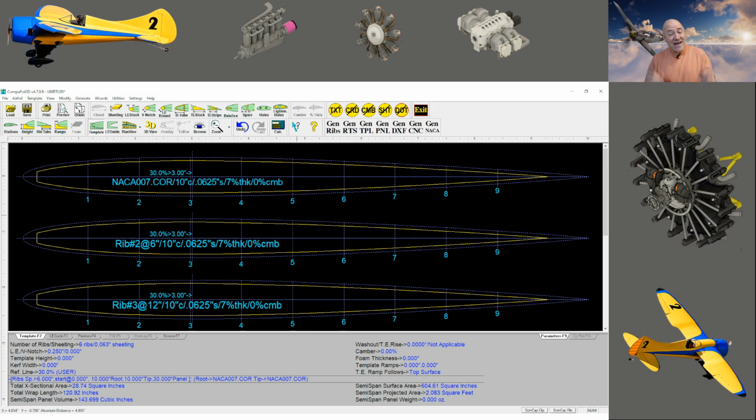But I use this 99% of the time for my vertical stabilizer. People always forget about the airfoil shapes of the stabilizer. Some people want the horizontal stab to be a flying stab, which I've seen a lot of people do. There's a lot of controversy, and as the plane goes faster, both surfaces are flying. And I'm not going to get into that because that's a huge rat's nest. But this is the airfoil I love for my vertical stabilizers.